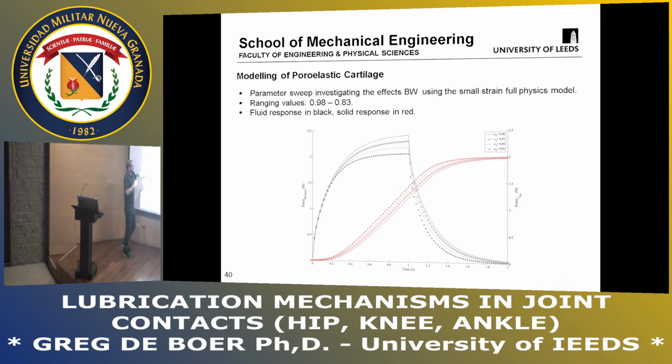So as I include extra terms, I start to shift the maximum pressure up, and I start to push the solid response further to the right. So what this really showed was that when we're considering this type of time period of loading, so a 1 second time period with a compression of about 10% of the material, we do indeed need to include these extra terms to have an accurate description of the response.